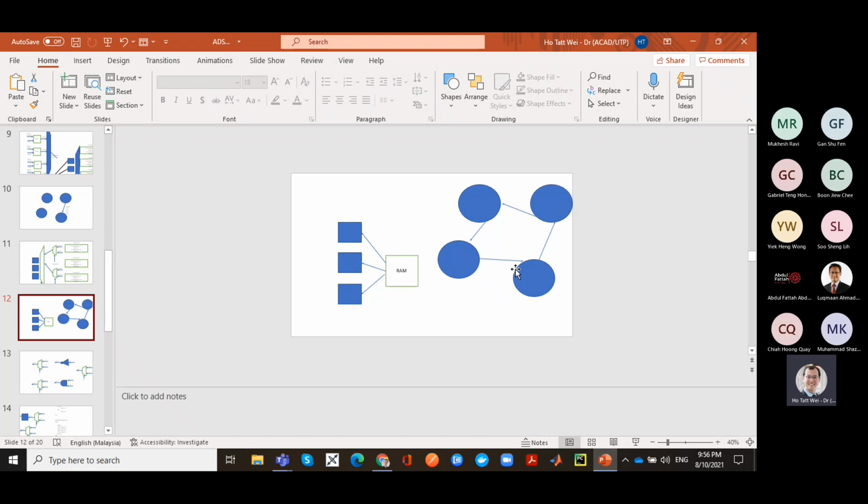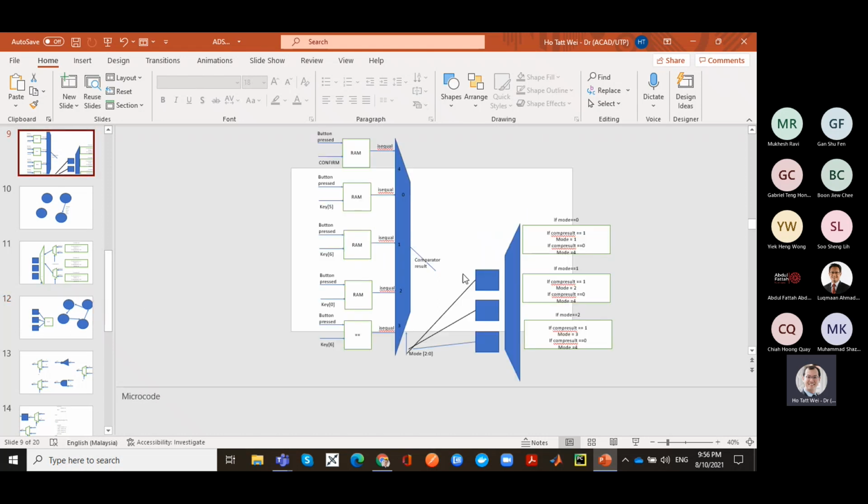That means I can implement a totally different state transition machine, a state machine, right? A state machine is nothing else but saying a sequence of modes, a sequence of states I'm operating, right? But I can change the order of the states, right? I can also change the encoding of the states, right? So if you interpret putting a lookup table feeding a flip-flop, all of a sudden you have a programmable machine, right? Programmable in what sense? In the sense that the modes, the sequence of modes in which you will perform the computation, can be changed just by changing the implementation of the state transition, right? And that is just by uploading or updating the lookup table, the RAM.